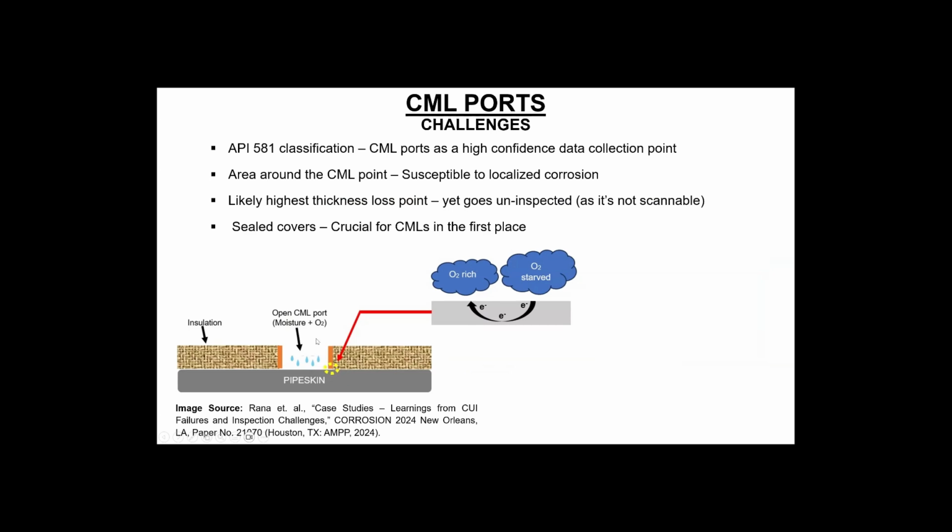Whereas the inspection person with the ultrasonic thickness probe would be mainly inspecting the area where the bad zone is, the one with the deepest pit. So basically, the person doing the inspection here is not capturing the worst spot, which is happening away from the scanning zone. In this case, we have data which gives relatively better thickness, but that's a false indication. So the data is no longer high confidence data. The whole point of explaining this is that if the cover is missing or not placed properly, it will eventually lead to pitfalls in the data quality collected from these inspection points.